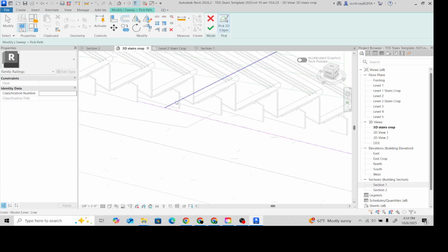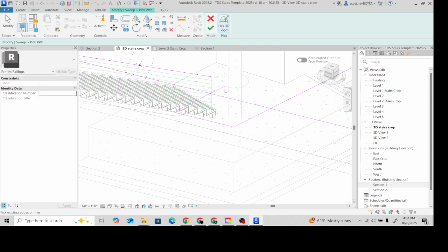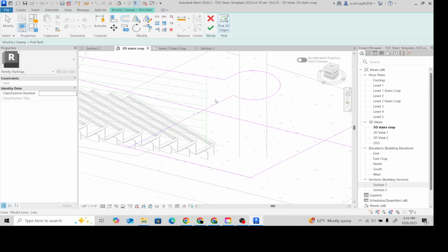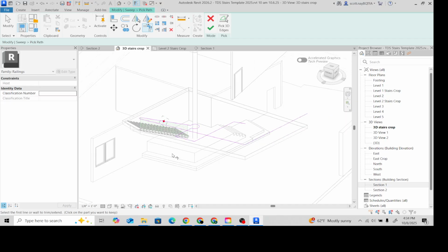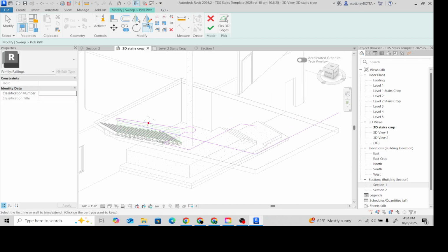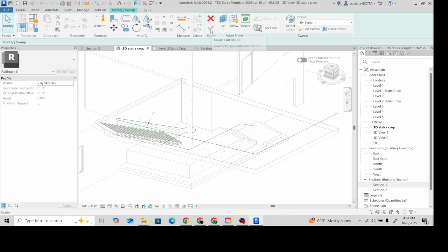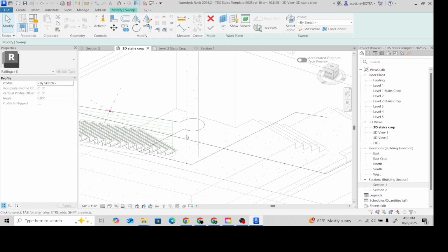And now I'm seeing that this line goes past. Now that it's magenta, it's easier for me to see. I don't need to stop everything. There's still a trim tool available. So I can click these two. Now in theory, I have a fully enclosed clean sweep. I'm going to click the green button, and the fact that it's telling me I can draw tells me that all of these are connected in a way that Revit will work with.